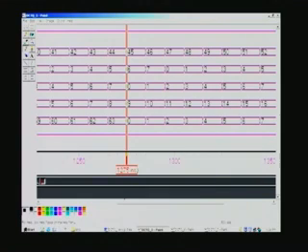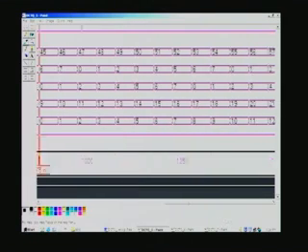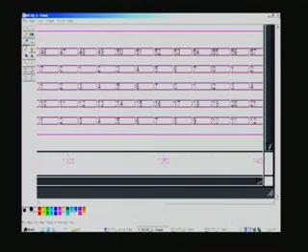The start of the block was at 635 nanoseconds we have seen. If you take the difference, you will get precisely 640 nanosecond. If you divide by 10, you get 64 clock cycles. So, exactly our claim was every coefficient is created at every clock cycle. So, this is proved and it keeps going there, and we have some more waveforms.